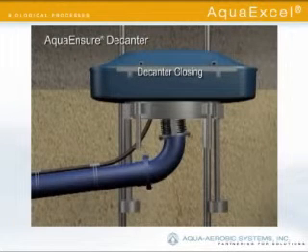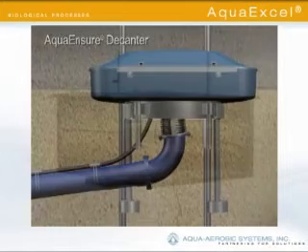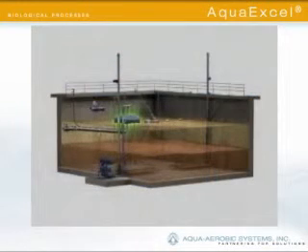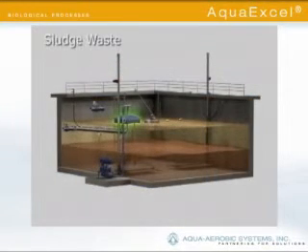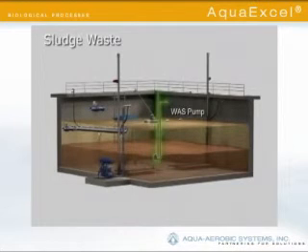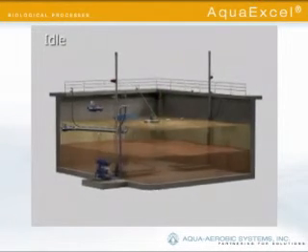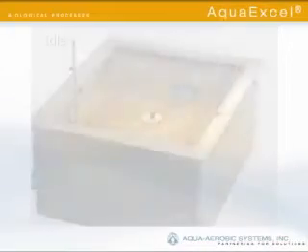In the final minutes of the decant phase, a small amount of excess biological solids will be removed or wasted to the sludge holding facility. This process is typically carried out with a small submersible pump, which operates for only a few minutes per cycle as needed to remove the thickened sludge. Under most flow conditions, the decanter will lower the water level to the minimum level prior to the expiration of the decant phase time, and the reactor is now ready to receive the next batch of influent. The final minutes will comprise an idle step, where the system allows the companion reactor to complete its react-fill phase.